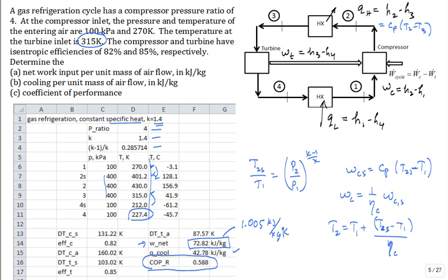Now, there is discussion of CO2 as a working fluid in refrigeration systems, and a lot of people are working hard to see that come about. Why? It's not from a performance point of view, it's from a holistic environmental perspective: you can release that refrigerant and it doesn't have an impact, like releasing even some of the newer refrigerants, like 134a. Okay? All right.